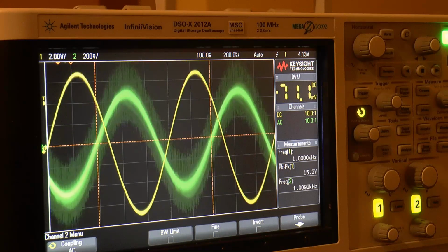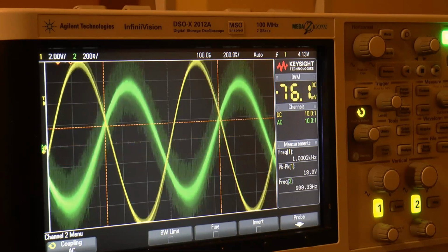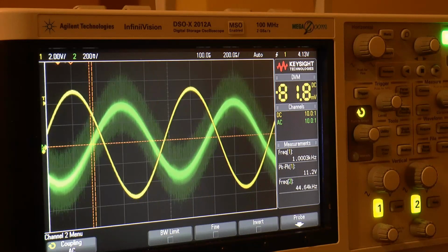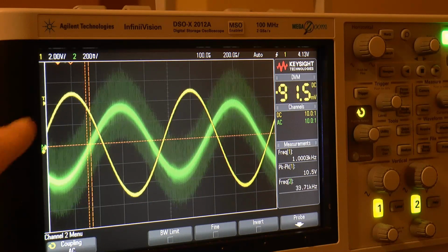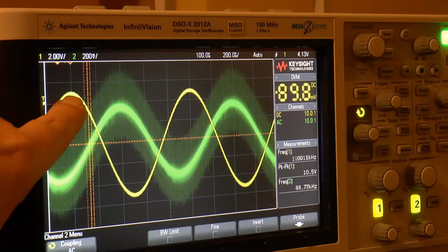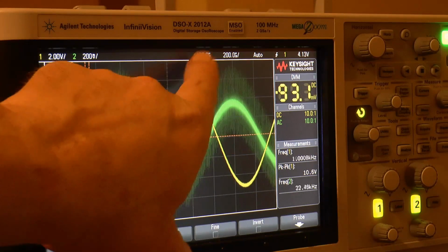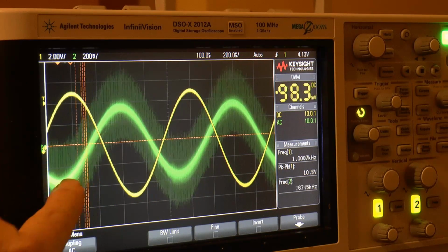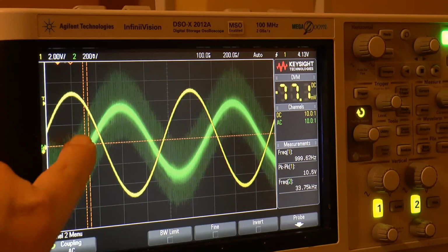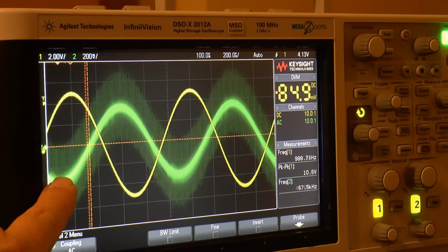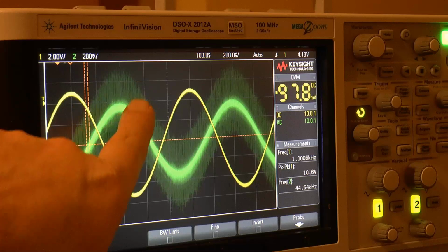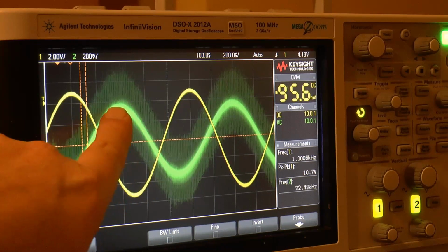This is actually being amplified through the amp now. So you see the bass here lined up on these marks, these lines, there and there. So this treble is actually nearly 180 degrees out of phase. If it's 180, it should be in the middle of this square, but it's just to the left.